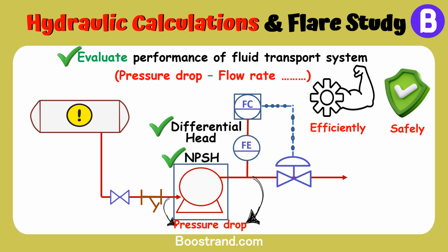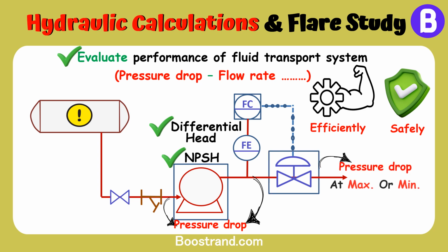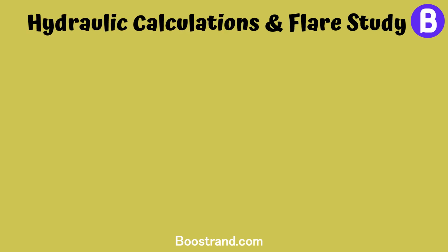If we want to properly size a control valve and estimate its pressure drops at maximum and minimum flow rates, this would need another hydraulic calculation, and so on. The output of these calculations should be reflected in pump and control valve datasheets in order to be considered by the manufacturers. Hydraulic analysis is also needed for the relief system.